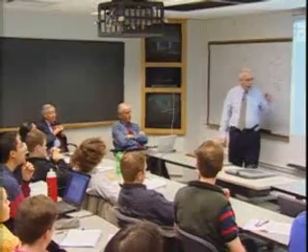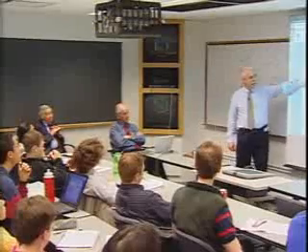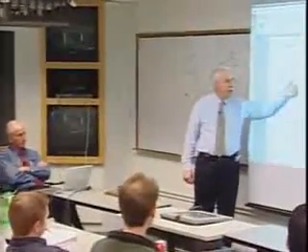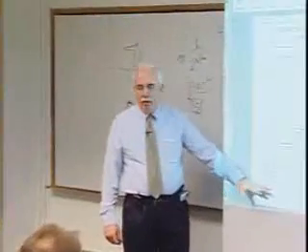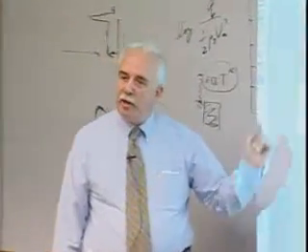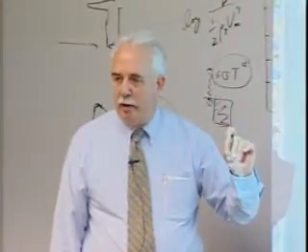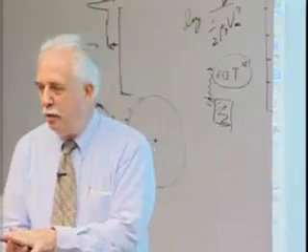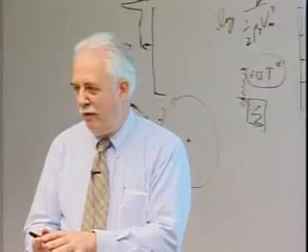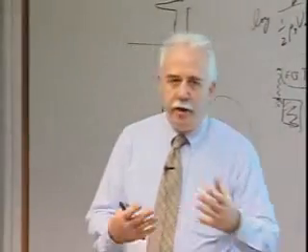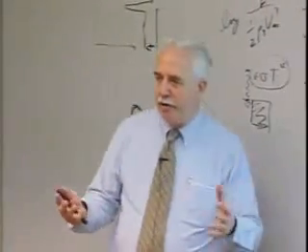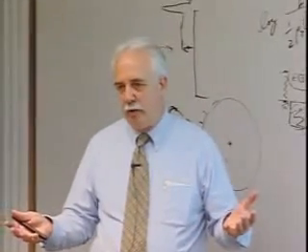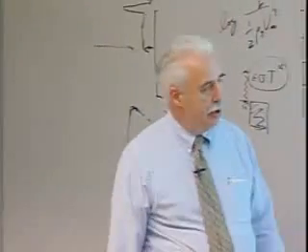Right. And I won't spend much time other than say we first looked at smooth body transition. This is heating rate versus distance. Smooth body. And then we put roughnesses in. We actually went to cryogenic models with simulated tiles to get that boundary layer sucked down to be a little better simulation of flight. The alternative was to put bowling balls on the surface of the thing to try to trip the flow, and that didn't have anything to do with physical reality. So there's a lot of work there.